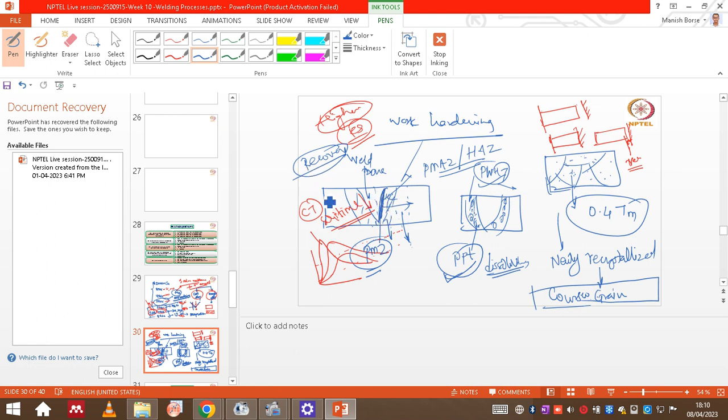But for materials like aluminum alloys, in the surrounding region, the heat affected zone, the material undergoes dislocation annihilation, and because of that the base metal properties will be decreasing, right? Another strengthening mechanism of the aluminum alloys is the precipitates. Whatever precipitates are there in the inner fusion zone will simply dissolve because we are melting the metal completely, right? And they will renucleate by certain post-weld heat treatments, okay.